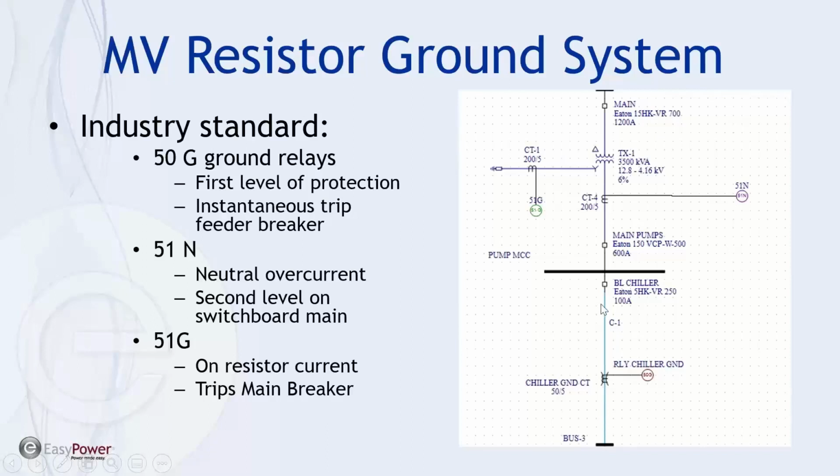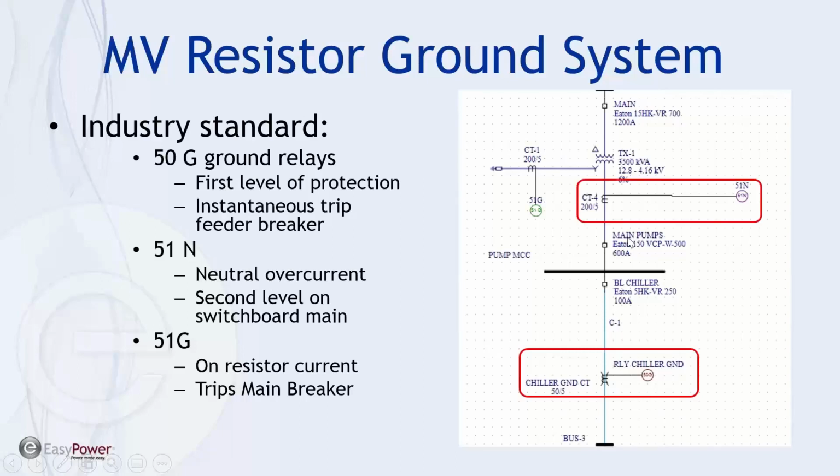And in this case, we're looking at probably medium voltage motor controllers or transformer protection downstream. And then to have neutral overcurrent protection as the main protection for the subsystem or switchboard or motor control center. So these aren't backup. These are literally zone protection devices.